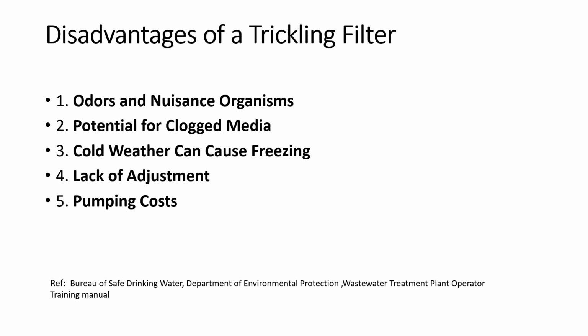The problems or disadvantages with trickling filter: excessive organic loading or inadequate ventilation can lead to anaerobic decomposition, which causes objectionable odors, smells. And here, filter flies and other insects can flourish well around the trickling filters.